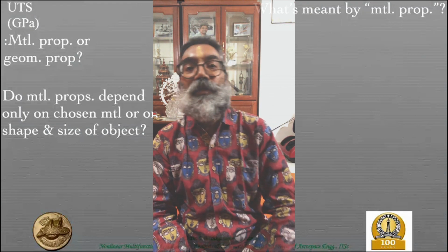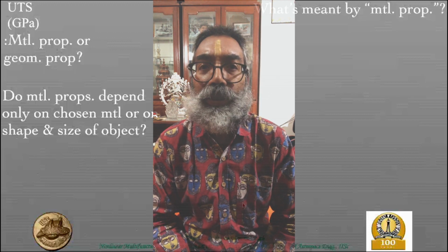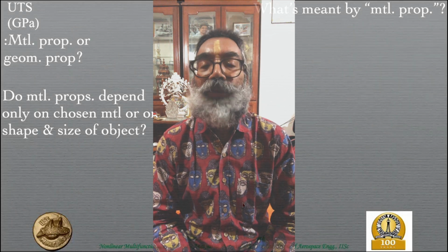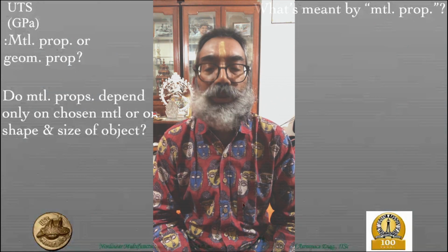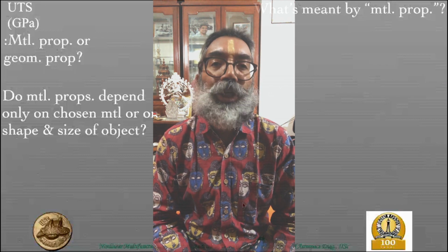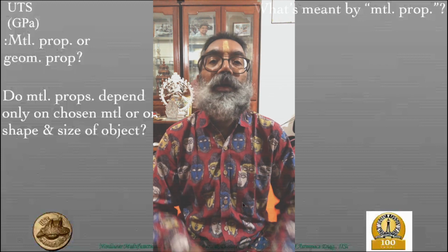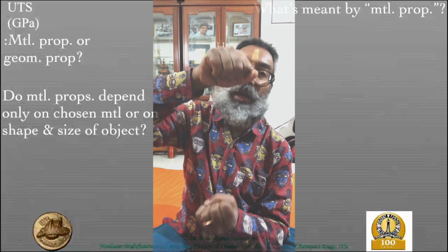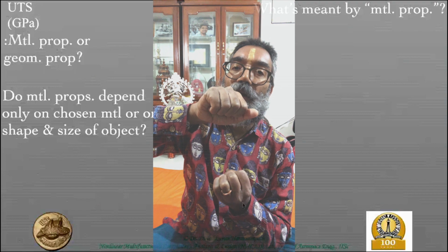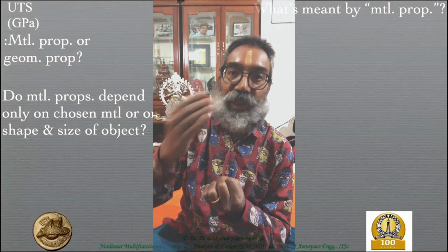Okay, good, fair enough. That's a very good point you brought up in terms of the ASTM standards. There are very clear definitions for the specimens to be tested, in terms of their shape as well as their sizing, and your dog bone shape, as you said. The dog bone shape is more to ensure that Saint Venant's principle comes into the picture, that irrespective of the way you're applying the load, which is also defined in the testing standards, in the interior region the stresses are larger.